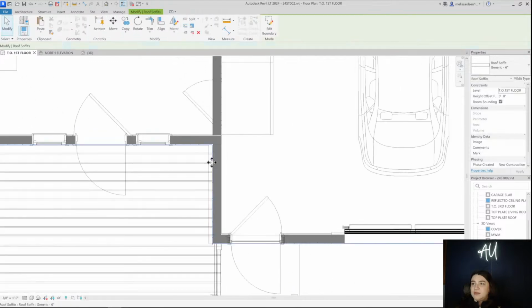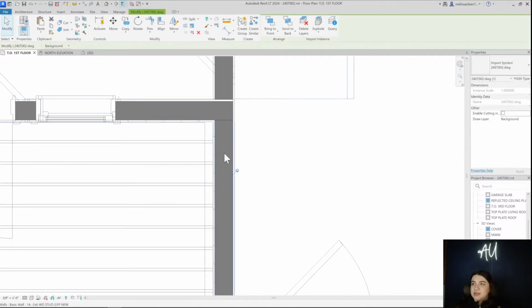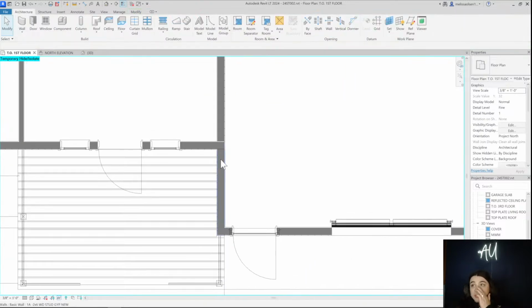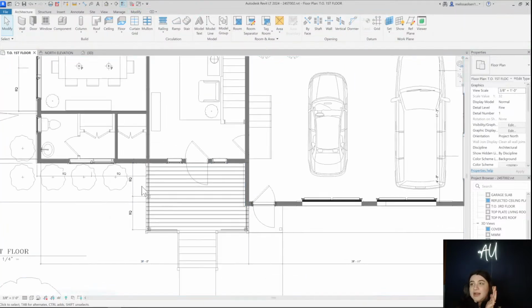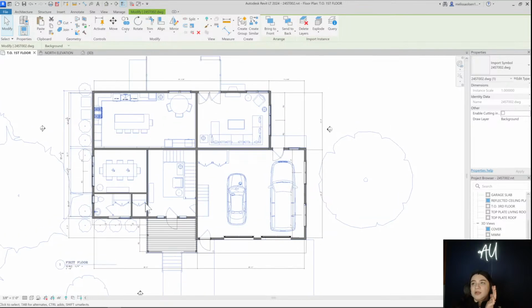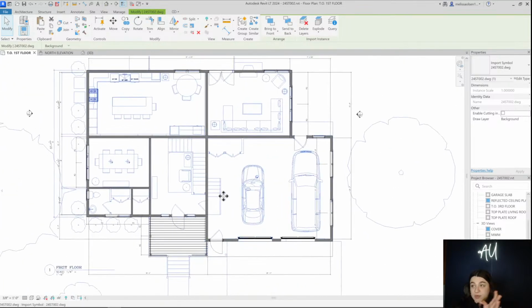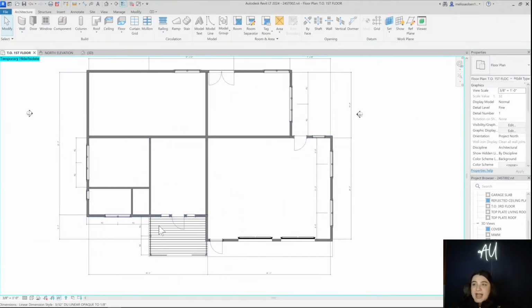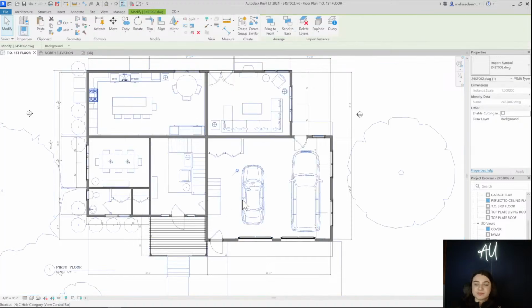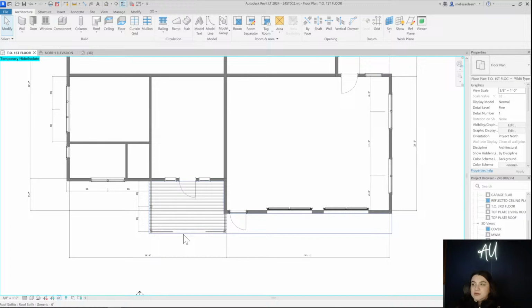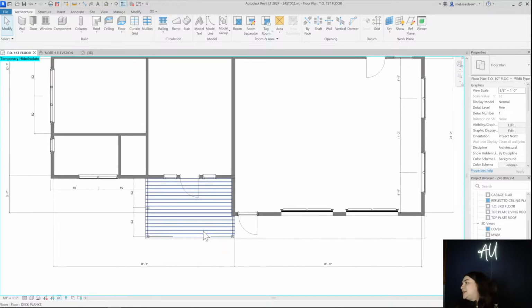The roof above. What is this? Pinned. It's hard. There's so many lines when I have the CAD file on, and I don't really need the CAD file on right now. This is just all Emily's details of like furniture and all those things, and we are just focused on the exterior right now. I had it on because we were figuring out where we were going to place windows and the elevation. So I'm just going to close that. Temporarily hide it. And temporarily hiding things is just HH in Revit.